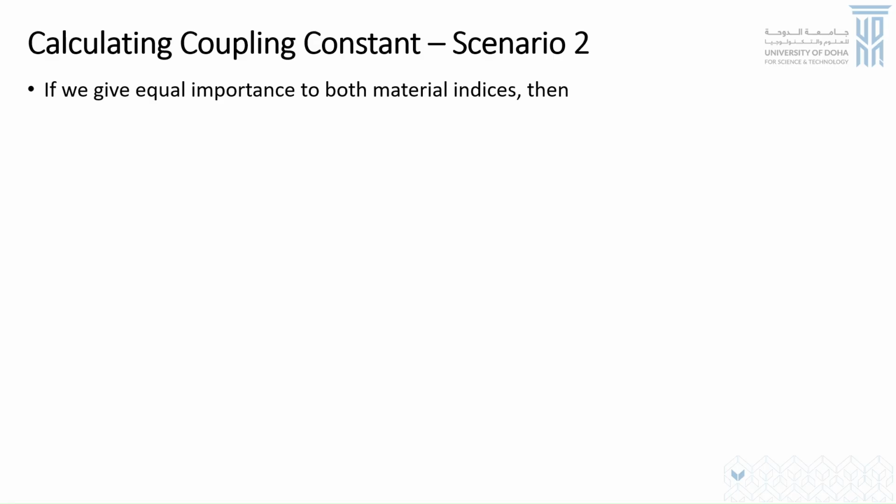So in some ways, you can also think that we are actually valuing the strength more in this particular case, because really the deflection, once we know the static deflection, we are trying to just work with that to keep our impact force in a certain limit, and we don't want to unnecessarily put extensive constraint on the deflection itself.